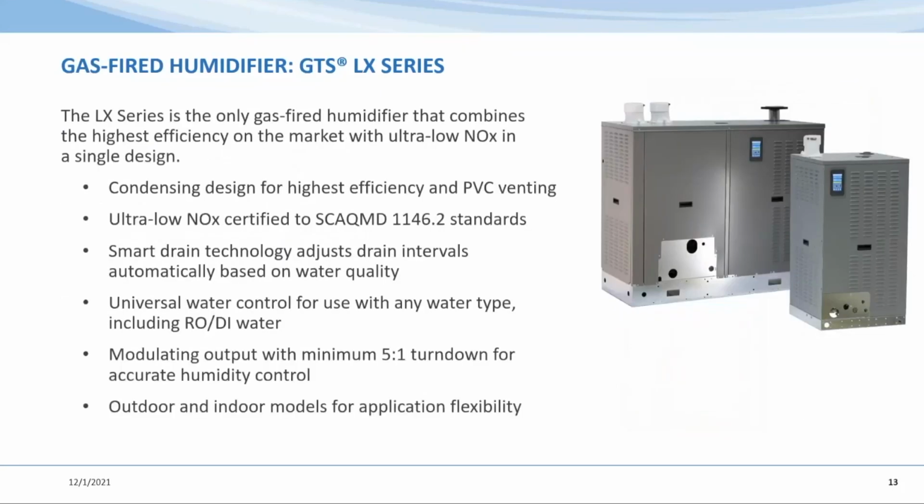Going into the gas-fired humidifiers, the GTS LX series is the only one on the market that combines the high efficiency aspect with ultra low NOx in a single design. This has been beneficial for many of our customers regarding having both of those standards and having it certified. What this does for the high efficiency piece and condensing design is allow for PVC venting, which can be a great cost savings compared to running materials that are better suited for high temps, such as galvanized or iron-based piping.